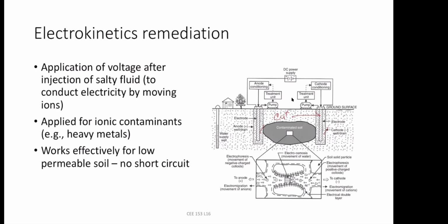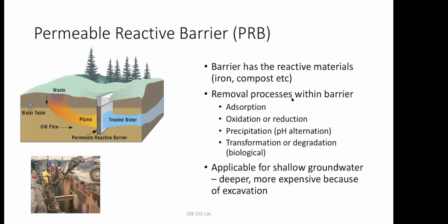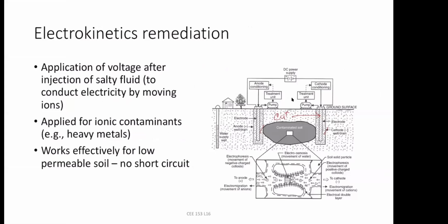Why is it efficient? Think of pump and treat, advanced oxidation, everything we talked about. You keep putting the reactive materials near the location which is polluted. A lot of the time the clay will hold those things, so it's very inefficient for water to move out of the system, and you cannot really treat those locations. Whereas here, you don't really care about water because water doesn't have to move. All you care about is that the ions or the pollutant has to move out of that water. So that's why this is very efficient when your soil has low K, low hydraulic conductivity.